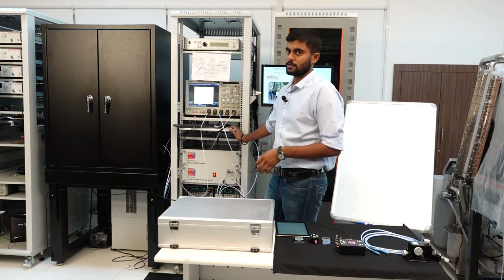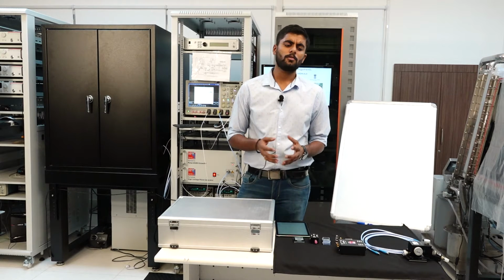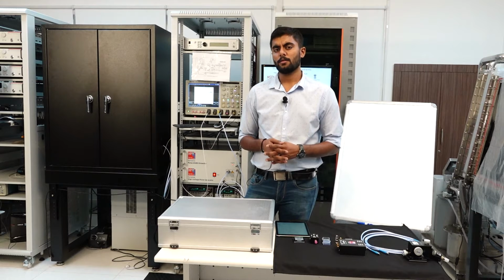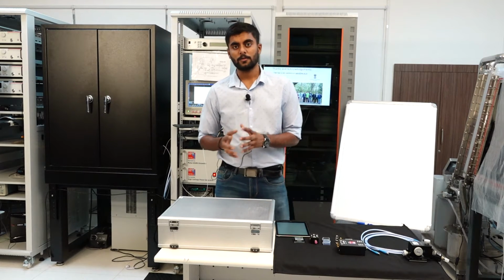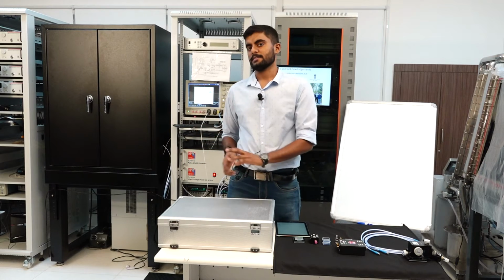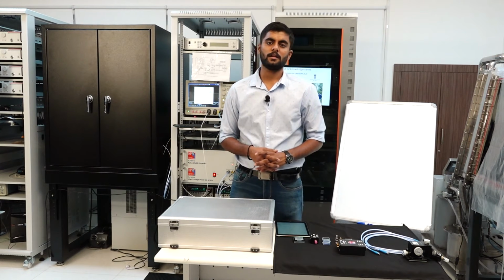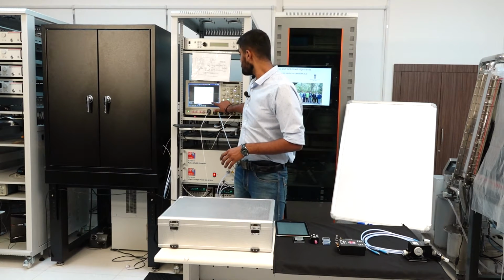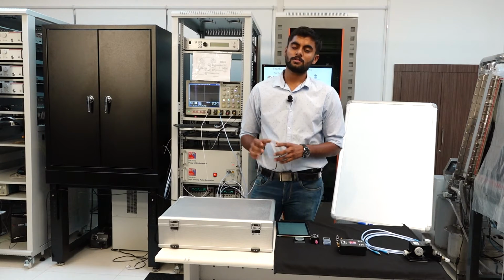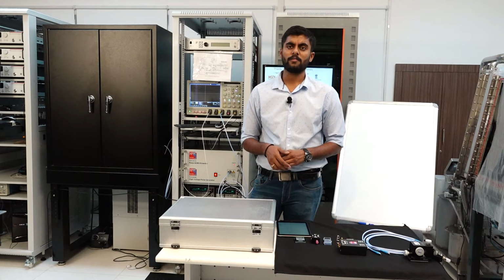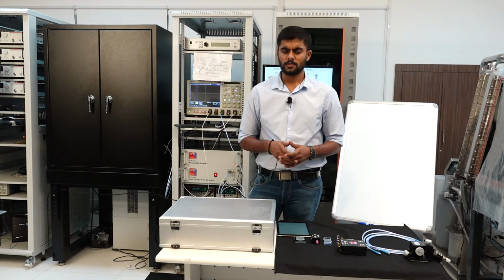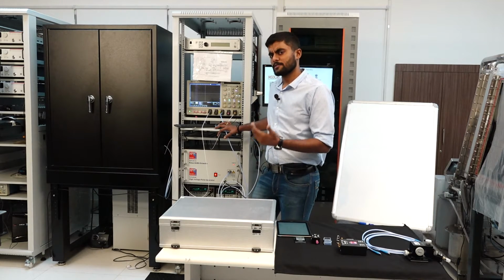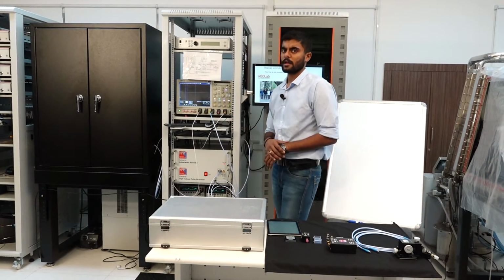Another important component here is an oscilloscope. So whenever you're talking about waveforms, you would also want to capture these waveforms. You can capture some data, but it's always more intuitive and it's better to capture the whole waveforms if you can. And that's where the oscilloscope comes into the picture. Whatever I'm going to apply to the device under test, and I'll show you in another video how these measurements are done, whatever you apply, whether it's current or voltage, will also get captured in this digital phosphor oscilloscope here. The oscilloscope that we use has a very high sampling rate, around 25 gigasamples per second. And there are different variants of oscilloscopes available in the market. These oscilloscopes are used to capture the different waveforms, applied, captured, measured, whatever you want to capture, you can capture in this.